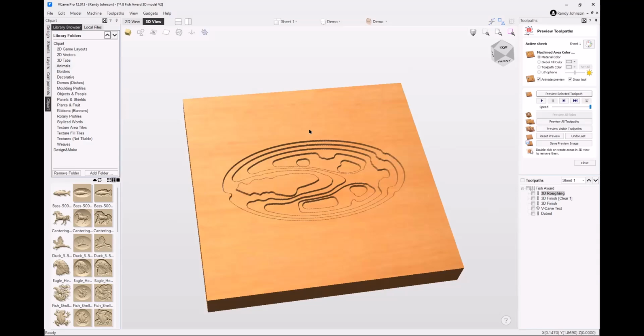A down spiral bit is a more unique bit, and it has a couple specific situations. One is if you're cutting through material that has real sensitive veneer on the top, then a down spiral bit will make that clean cut guaranteed. The other way a down spiral bit is most useful that I use it for is when I'm cutting 1/8 inch plywood, because that down spiral actually pushes down in that thin plywood and keeps that plywood from lifting up, which an up spiral would.